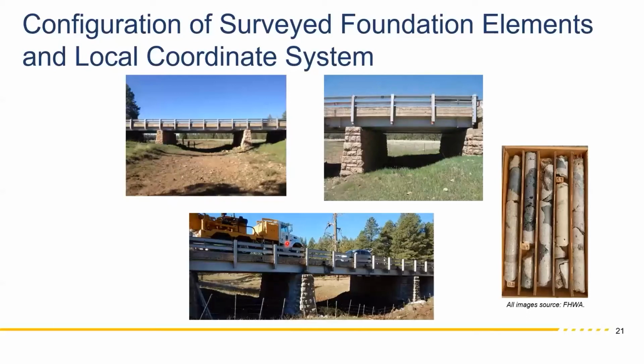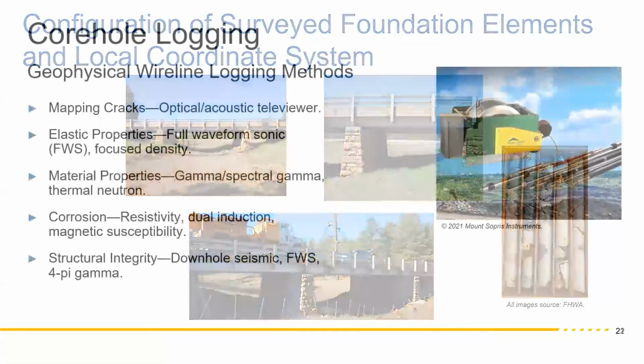Okay, so what we did, we cored from the deck all the way through the steel girders, all the way through the bedrock, through the foundations. We put a pair of cores for each of these foundation walls. And what was the coring cost? It was about $150 per linear foot. So a 50-foot coring costs us about $7,500, so a pair costs us about $15,000. So there's a way of doing that, and there are a lot of lessons learned, but it's very effective.